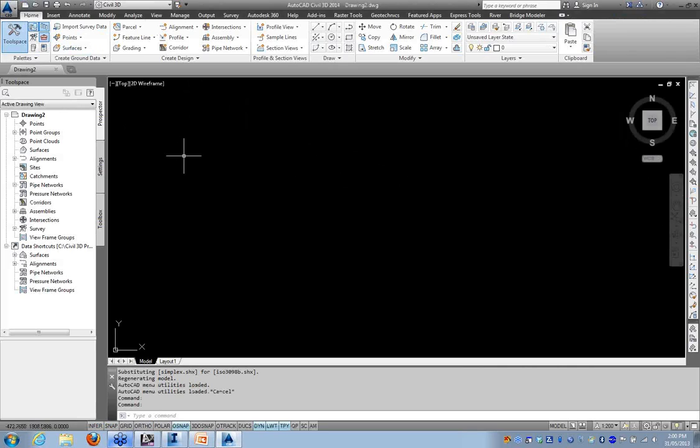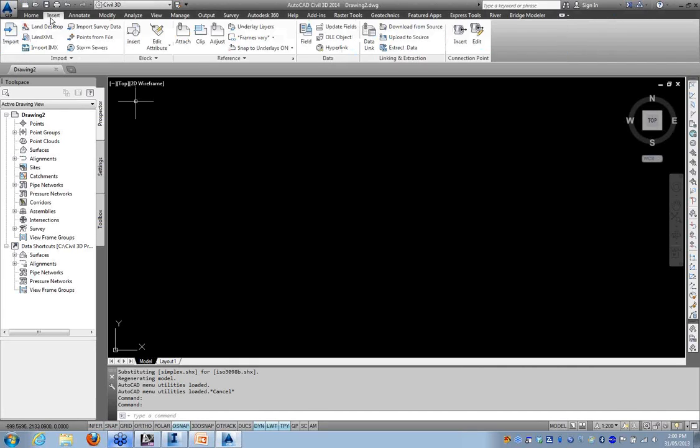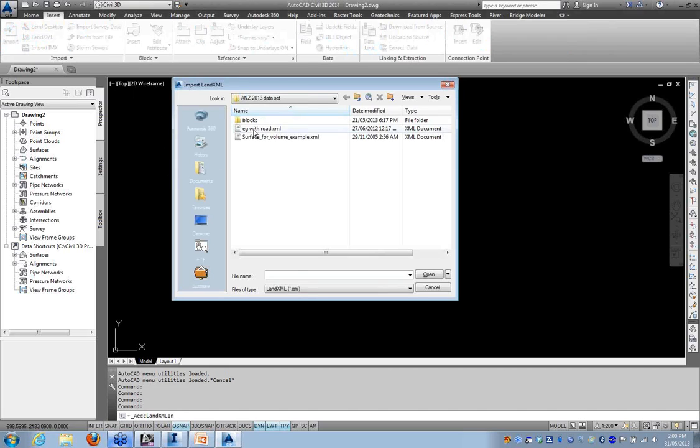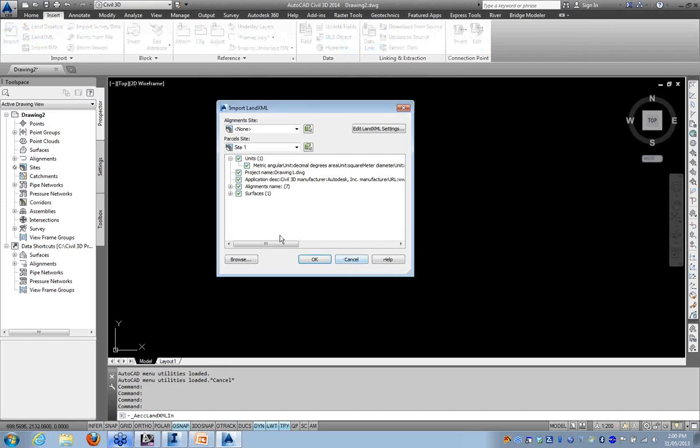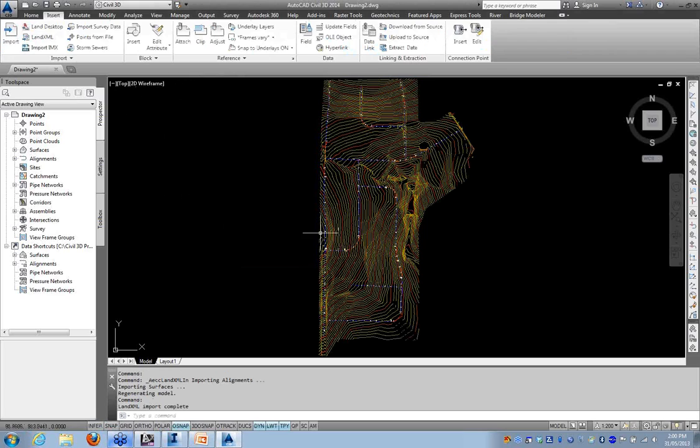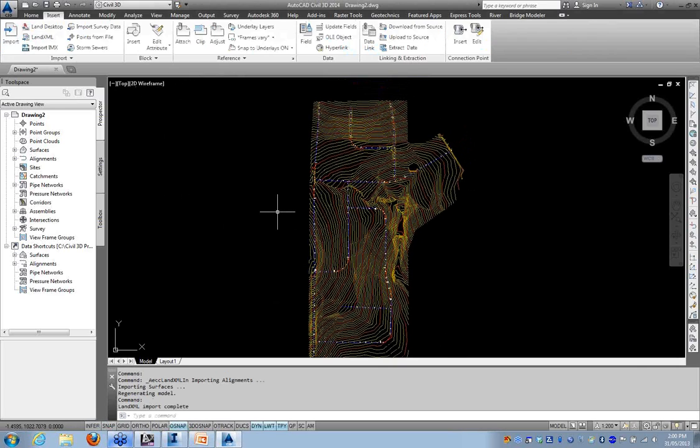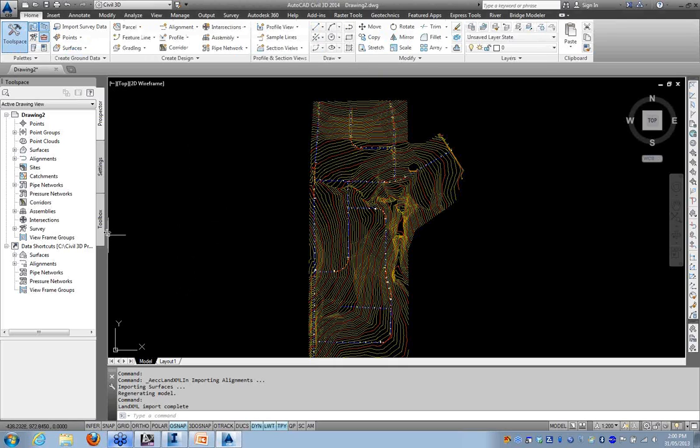So let's bring in our old favourite LandXML again. These are for rail turnouts, and actually it's in the toolbox where they're kept. If you've forgotten how to turn on that toolbox tab up in the tool space, it's this little button up here in the ribbon.